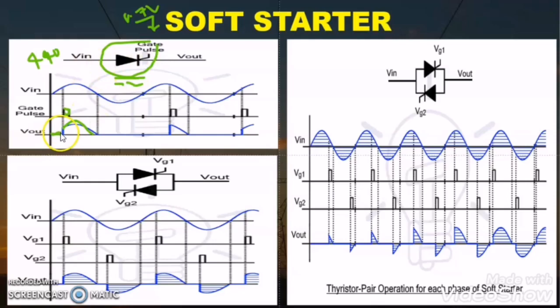So in this time there is zero voltage, and after giving a gate pulse the thyristor allows the voltage, and when the voltage reaches zero crossing, the thyristor again becomes an open switch. In order to have power supply in the negative cycle also, after zero crossing we again have to give a small pulse to the gate terminal of the thyristor. From the moment we give it, the thyristor becomes like a closed circuit, and it allows the power supply till the next zero crossing.